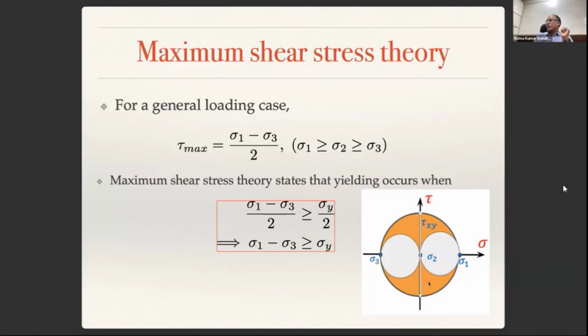state of stress, right? Unlike a uniaxial or a 2D state of stress, identifying the stress on a particular plane becomes a little more complicated here, but I am not going into the details of that. But you can clearly see when you look at this Mohr circle, the maximum shear stress will be equal to sigma 1, that is maximum principal stress, minus minimum principal stress, divided by 2. Sigma 1 minus sigma 3 by 2. Instead of just remembering it as sigma 1 minus sigma 3 by 2, you just consider this as maximum principal stress minus minimum principal stress by 2.